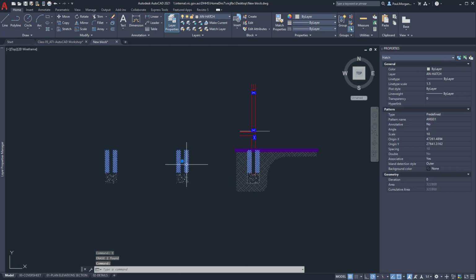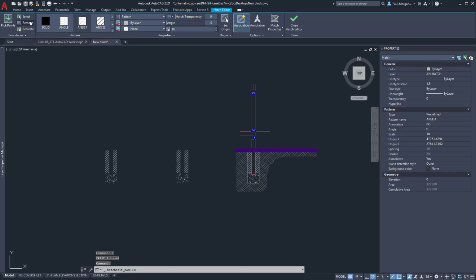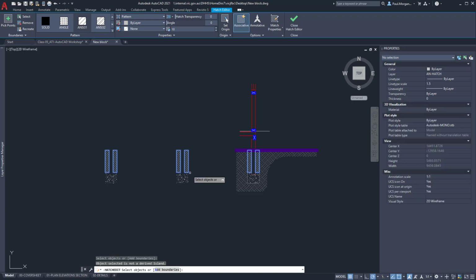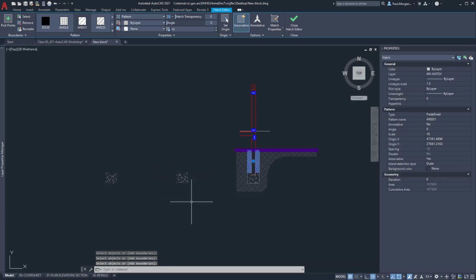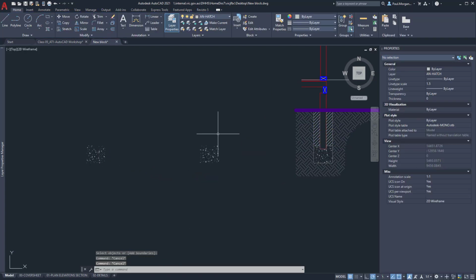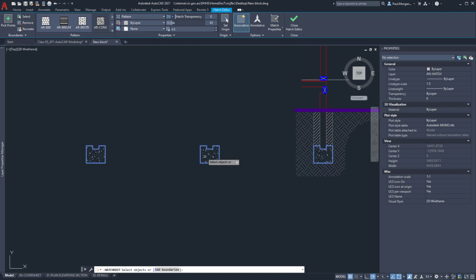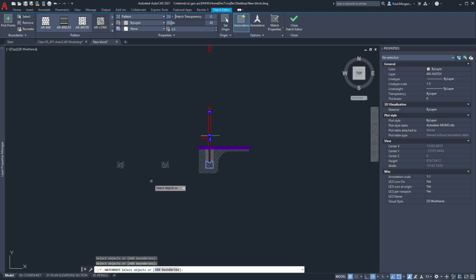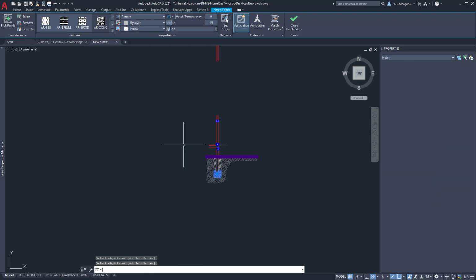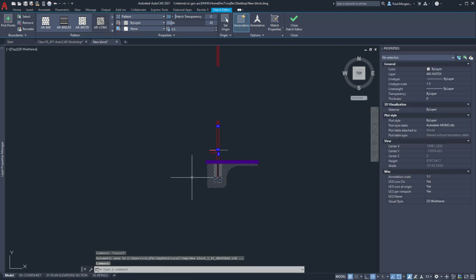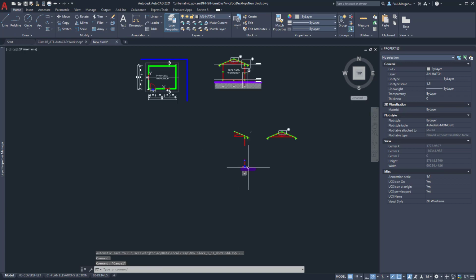And now I want to remove some of these. So I'm going to click on this hatch, click on remove, and then click and then enter. So I'll do that again here. I'm going to click on the concrete hatch, come up to here and say remove. Click on that, and then click on these boundaries of where the hatch was for the other drawing for the section, and then hit enter. And now I'm just left with the hatch that's shown here.